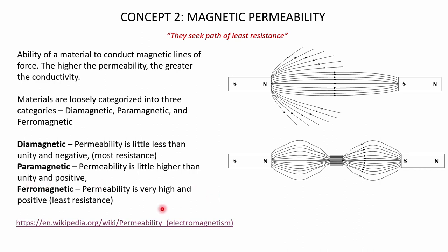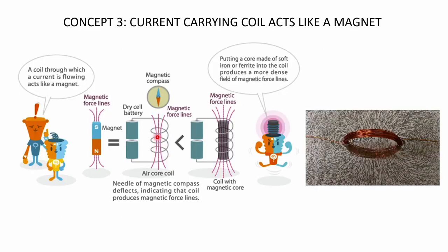This term is important because in the axle counter realm, you will see a lot of times vendors or suppliers say that they want the wheel to be ferromagnetic for their axle counters to work reliably. So the third concept is that in real axle counters, you don't have permanent magnets. Instead, you have coils, because when you pass current through a coil, the coil acts like a magnet. For experimentation purposes, you can do that too. Try passing current through a coil, put some iron filings around, and you'll see the iron filings orient themselves according to the magnetic field lines.